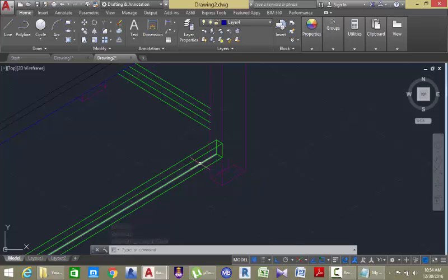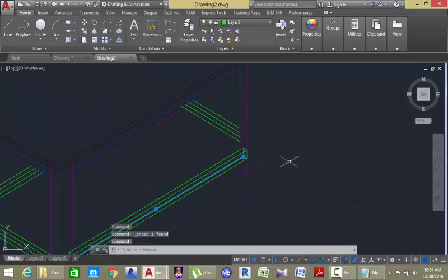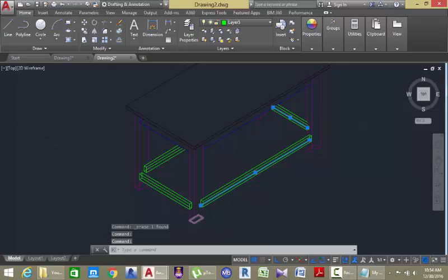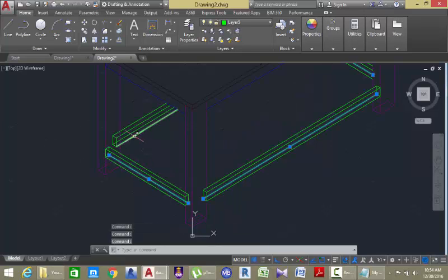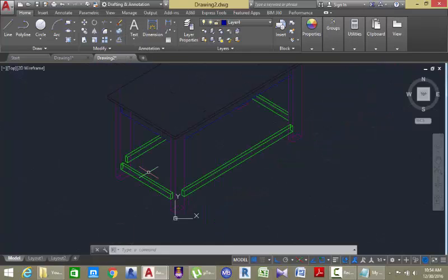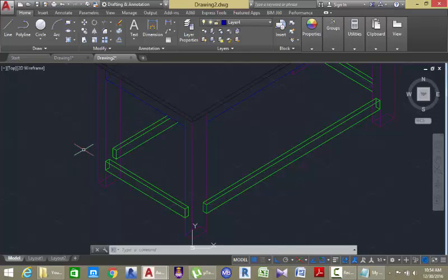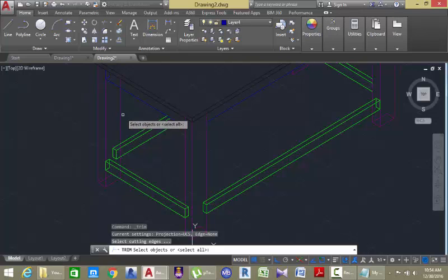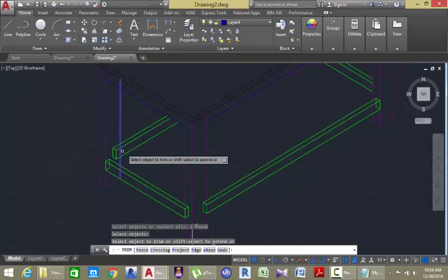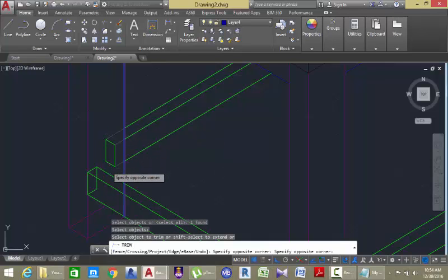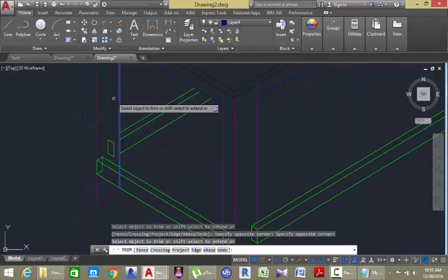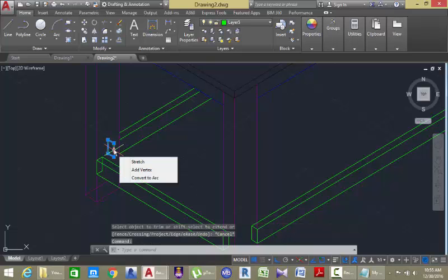Again, in the real world, you are not going to see this edge, so erase this edge. This edge. This edge. These edges are not going to be seen in the real world. Select them and erase them. Then anything that goes beyond this, from this point beyond this line, is not going to be seen in the real world. Select this, go to the Home tab, Modify panel, and select the trim command. Select this line, press Enter, trim all this stuff off. Press Escape, select this rectangle and press Delete on your keyboard.